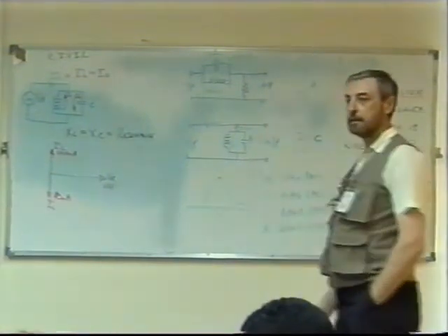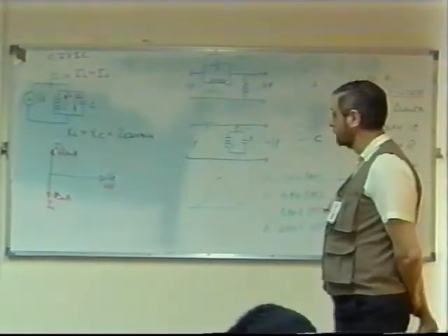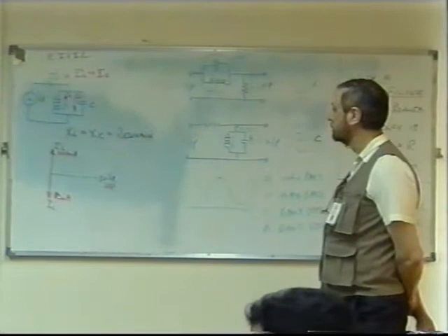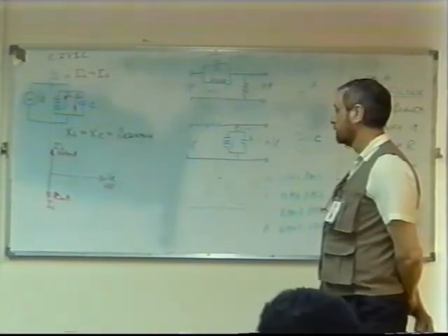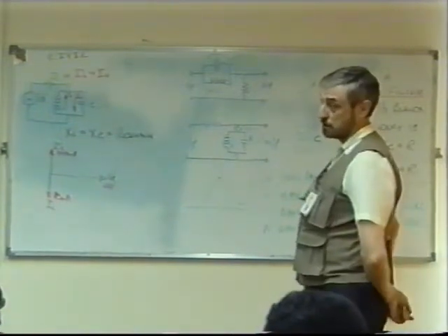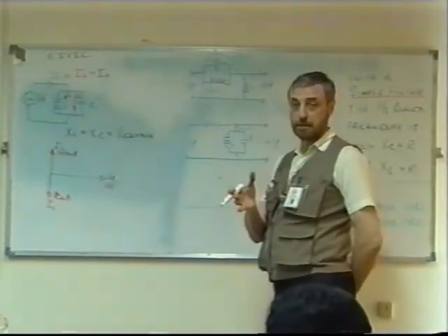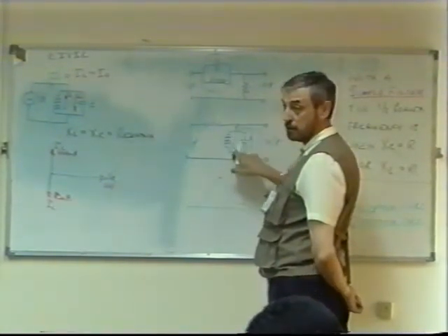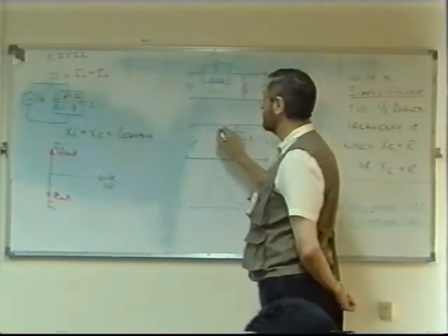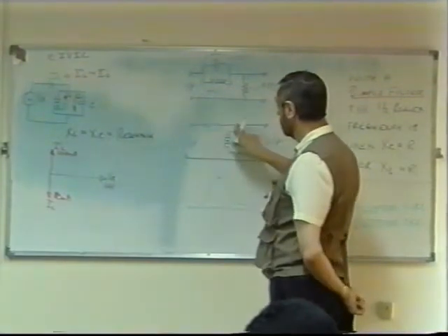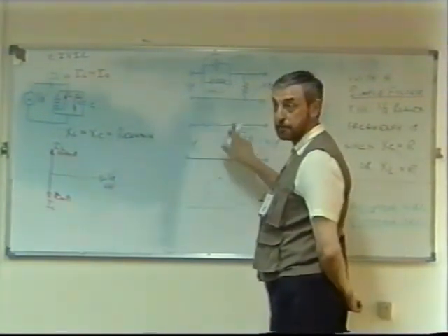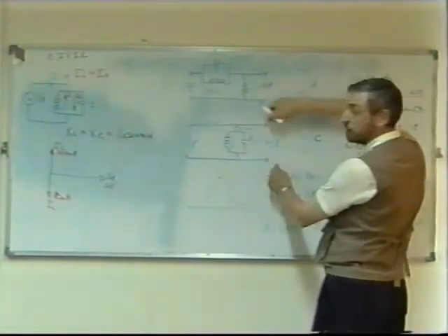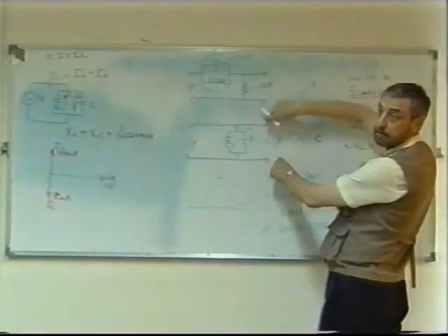The first point here, we have a resistor, and there is voltage at the input. Now what I'm saying is, if you find out what's happening at resonance, that's going to tell you. At resonance, this current is 0. If that current is 0, this current must be 0, because that's the only path there is for the current on the input circuit. If that is 0, VR must be 0, which means the whole of this voltage will appear at the output. Maximum voltage at the output.